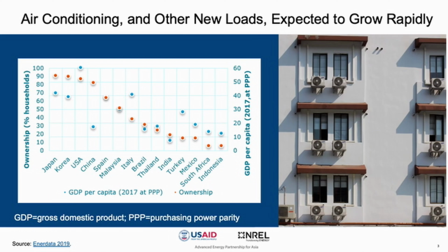We expect the intraday load peak for most countries with high air conditioning penetration to move from the evening to the middle of the afternoon, when residential and commercial cooling demand coincides. This may better coincide with generation from solar plants, but demand-side measures can also help lower peak load and overall stress on the grid.